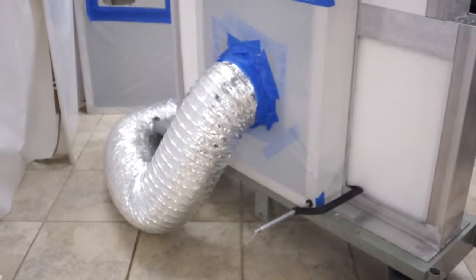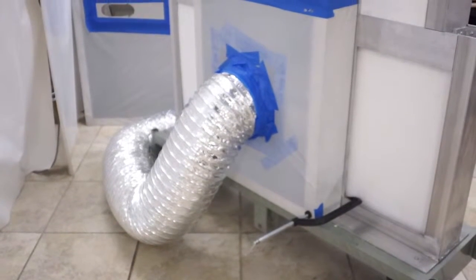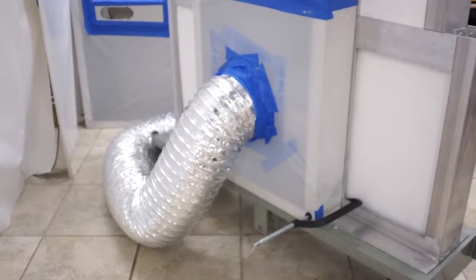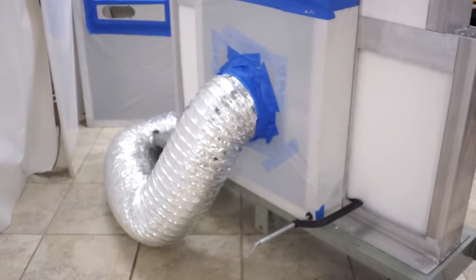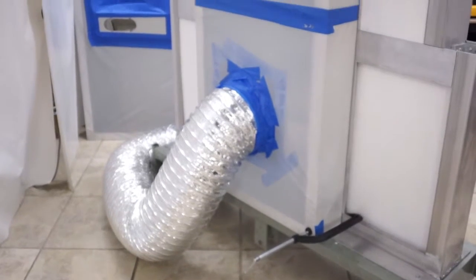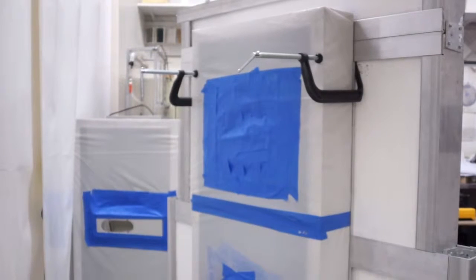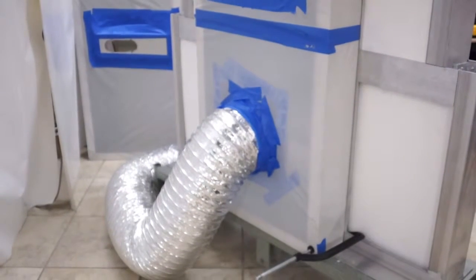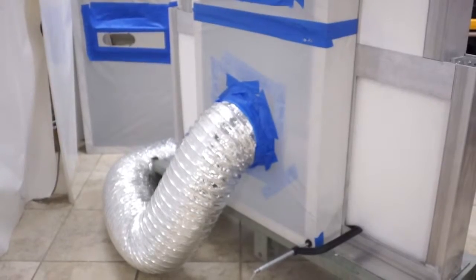This is the exterior part of the window mock-up showing the chambers attached to the exterior. We will run smoke into each chamber and pressurize it. Then we will go to the other side of the mock-up wall and measure the particles that pass through each of the windows. The top chamber has the standard window shielded by the backup window, and the lower chamber has the standard window alone. We will test the standard window now.